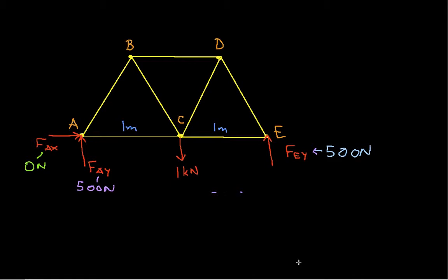And just as a reminder, as we go through this, we assume that at the joints that are put together by pins, there's no friction at any of the pins, so members are free to rotate any way they want to at joints, and that the members themselves are weightless. So you'll notice that we didn't take into account the weight of any members as we were looking at the bridge as a whole. In other words, we're assuming that their weight is negligible to the load placed on the bridge.